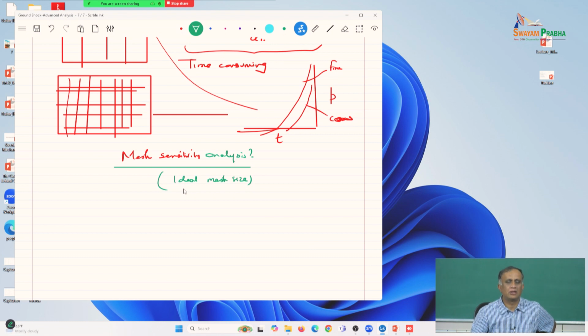Problems with concrete and the mesh size, it depends on many things. It actually depends on even your Lagrangian mesh sizes. Mesh sizes also depend on the type of material used. So, I have found, for instance, that for concrete, for the simulations we had, the 1-inch mesh size simulated the experiments best compared to even half an inch. You would think that as the mesh sizes keep decreasing, your simulations converge, right? It should converge, same deflections. Doesn't happen because concrete is a complex material.